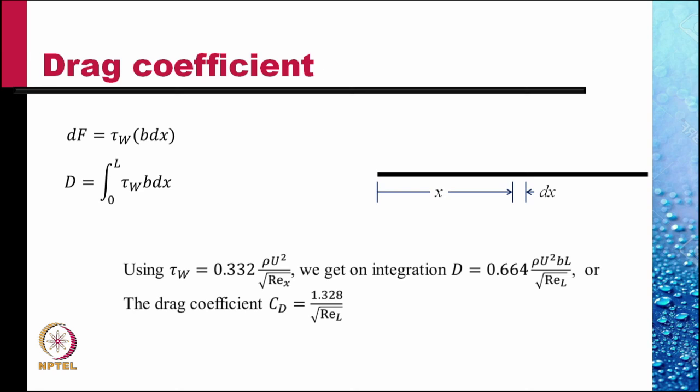Notice that for large Reynolds number, this drag coefficient is still small. So it does not lead to D'Alembert's paradox. We have neglected friction, we have neglected viscosity effects, and the results that we obtain would be approximate.